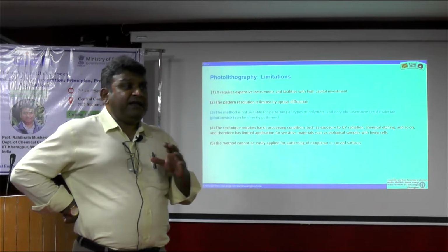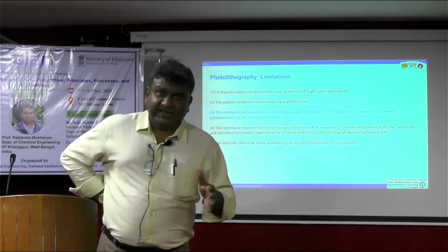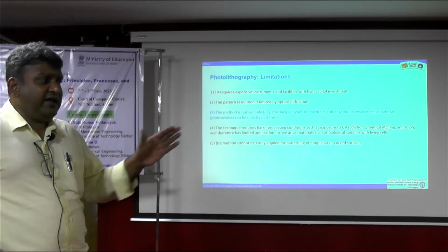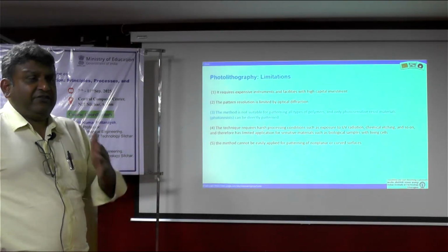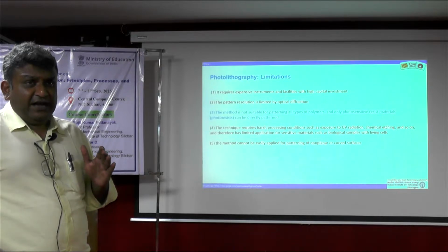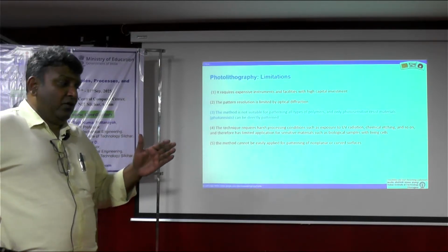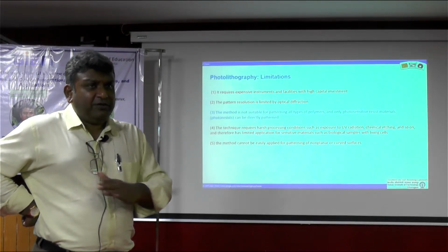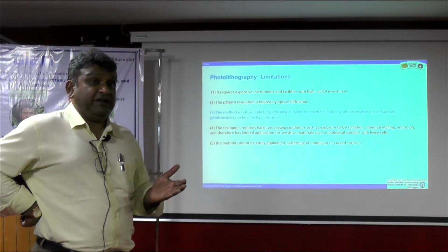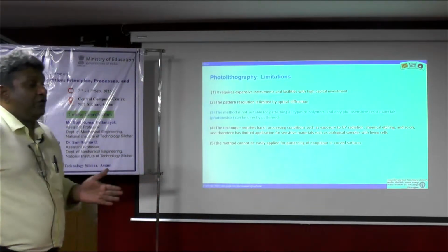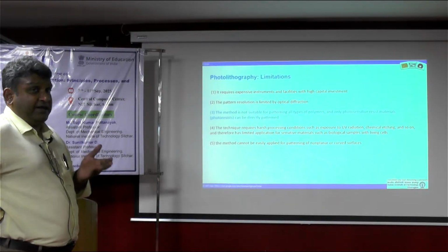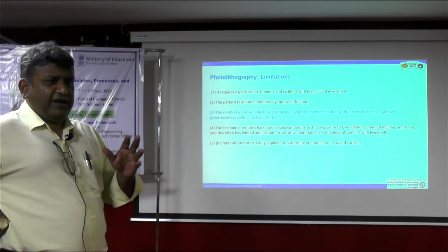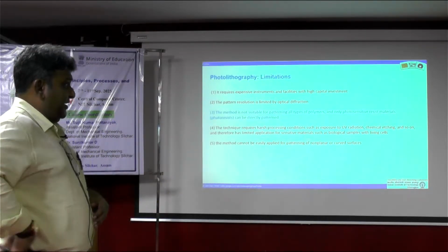But there can be many bulk nano applications of these patterned surfaces, where photolithography becomes exorbitantly expensive. And as I also told, it is only capable of patterning a photoresist layer. But there can be so many other types of material, including polymeric material, which you may want to pattern for doing some nice experiment or work or low-cost diagnostic devices, where photolithography may not be the best suited technique.